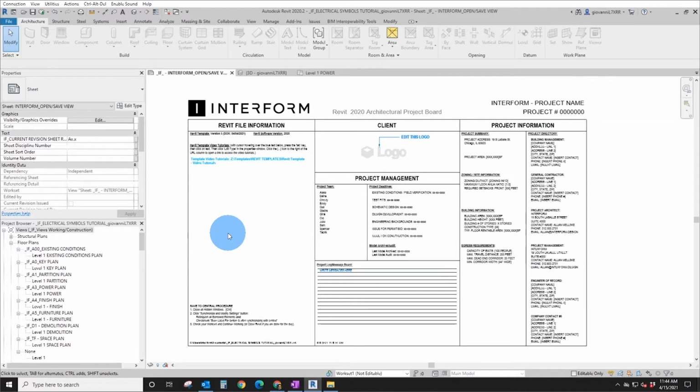So we're going to go over a basic overview of how they work, and then I'm going to go into separate segments on each individual family and really do a deep dive on how those are used and all the parameters that go along with each one. Similar to the door families that I touched on in a different video, the functionality and use of our standard families is very similar. Once you understand how one is set up, the others, even though they have different hosting faces and different family types, all function parametrically very similar.